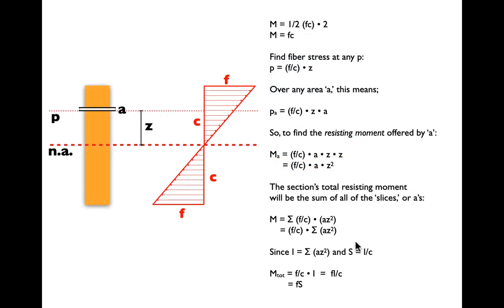Now, the section modulus is useful because we can go through and we can figure out the relationship between moment and stress and distance from the neutral axis to the extreme fiber. This is a lot of thought experiment here. I will go through this in a little bonus video. It will not be on any exams or problem sets. I think this is a particularly beautiful piece of math.